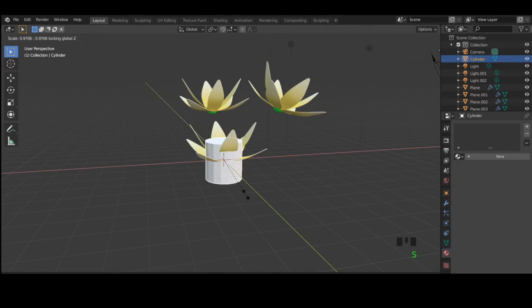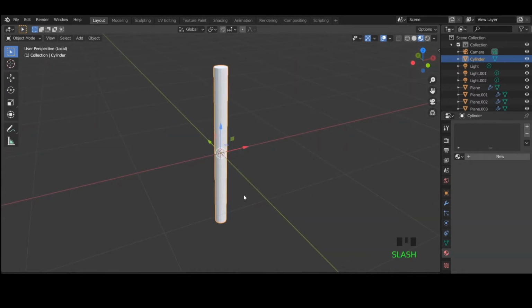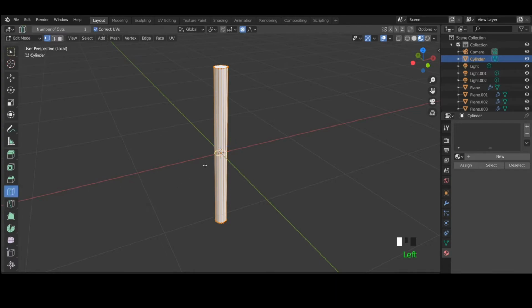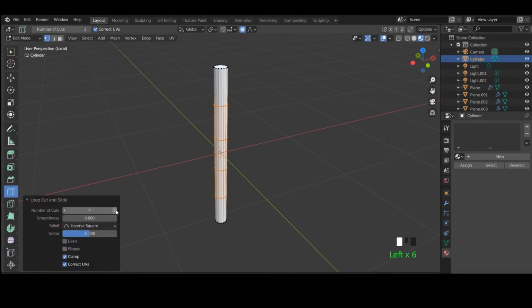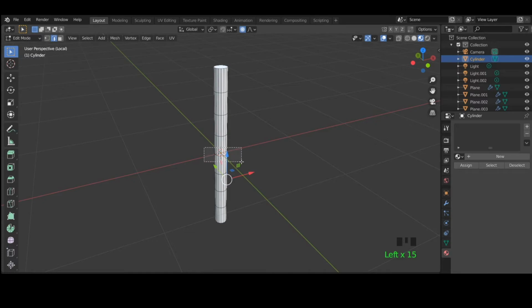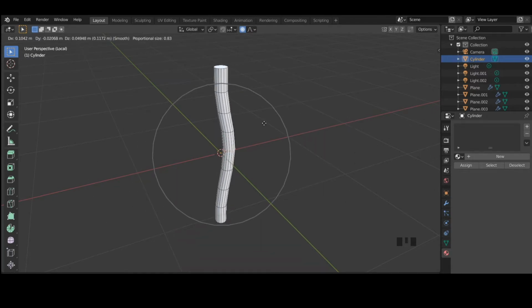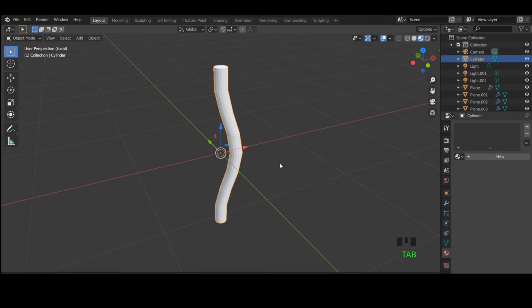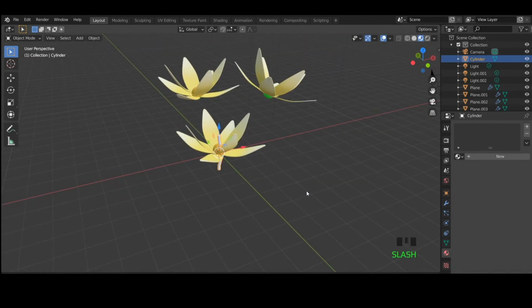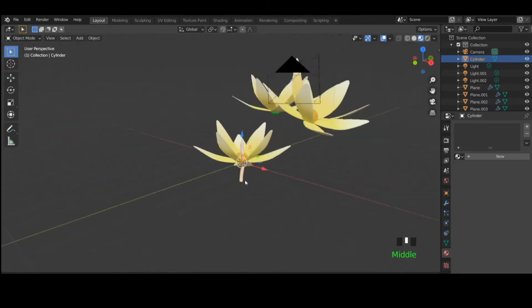Scale, Shift Z, so you are scaling along Y and X but keep the Z. Now / to get into individual mode, local editing mode, and then get into edit, get some loop cuts, and then select lines, maybe this one, proportional editing, grab, tab out of editing, tab out, slash out of the local editing.